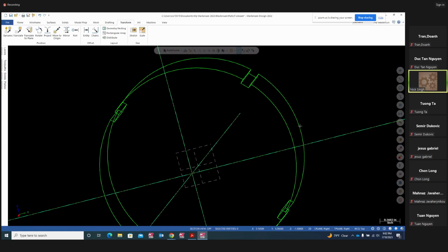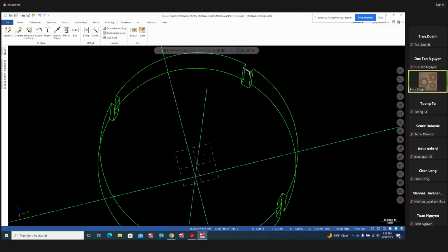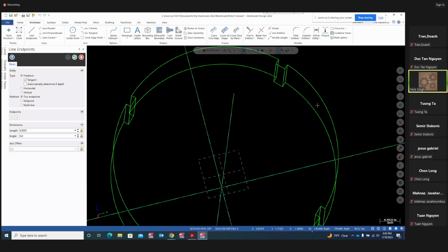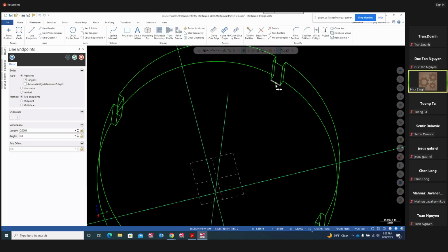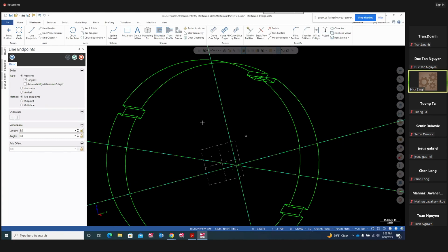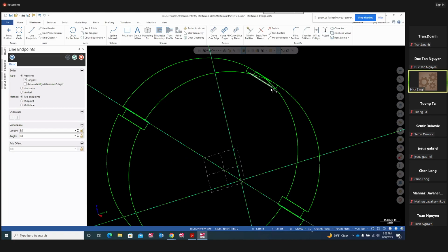So this is what I was telling you to create that tool path here, guys, cross contour. We have to go to 3D. I changed to 3D. We're going to go ahead and wireframe. We're going to create a line. So create a line from midpoint of this line to midpoint of this line right there. Look at that. So that's going to be my geometry for that tool. And do the same thing on this one too. And we can just go ahead and rotate that one line if you want to, but it's okay. From there to there in 3D, we can draw that line.